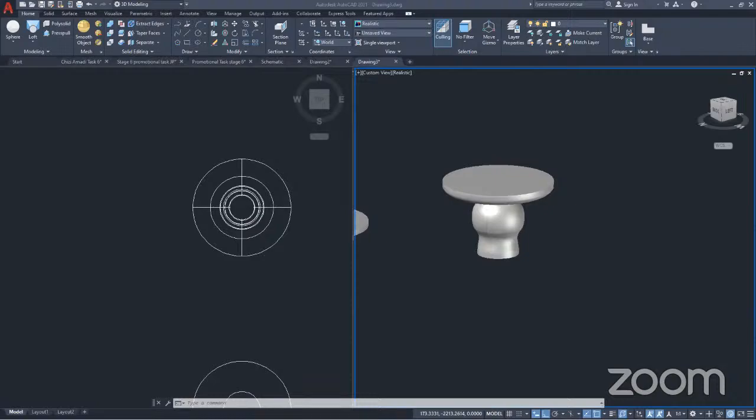Okay. At this point, what you can do is maybe just modify it with other objects and things. But at this point, unless maybe you want to go into mesh editing, it's always advisable if you're trying to achieve something with the loft or the revolve command, to make sure you have your 2D in place correctly before you actually make it a 3D solid. So you don't need to come back and be trimming off all those things.